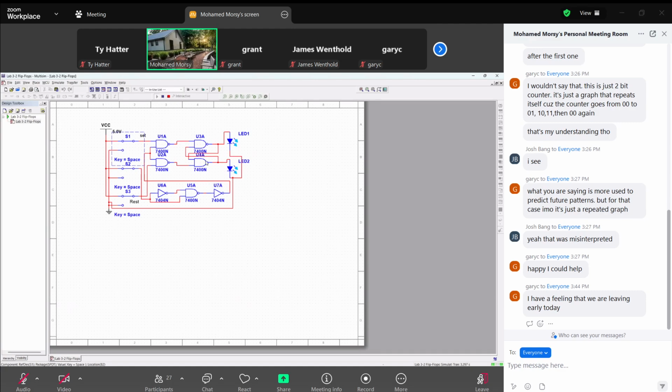My screenshot for 1, 1 is important to show that when you say in your comments it is not allowed, because as we see in the screenshot, both outputs are zeros. I mean Q and Q inverted, both of them are 0 at the same time, which means we don't know the output.